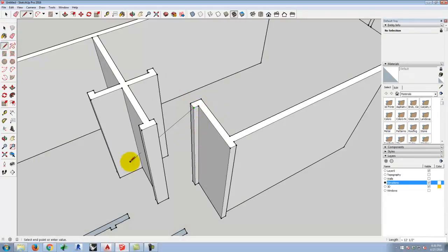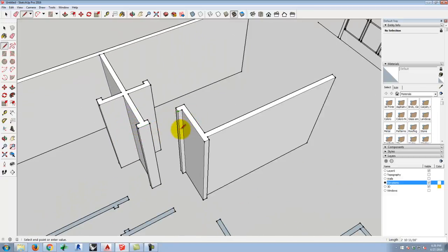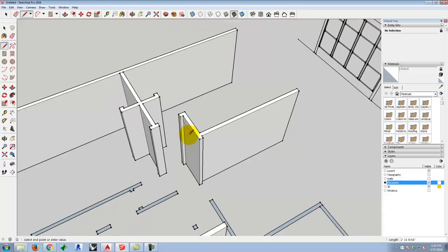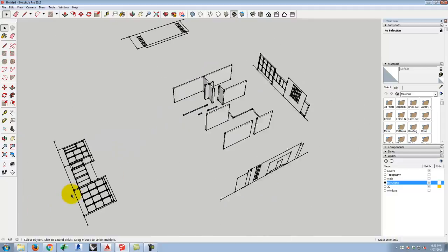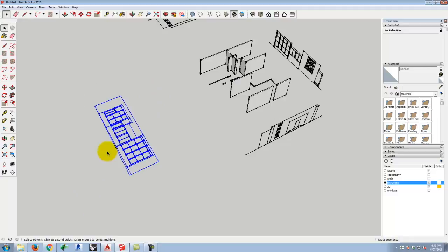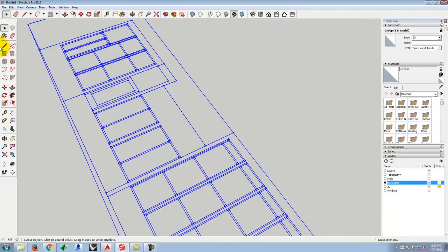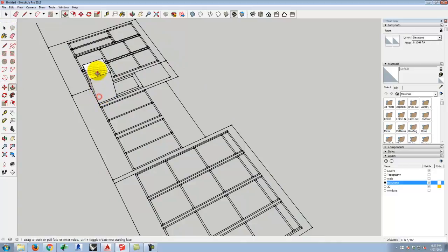So in this instance, my door is probably down at the 8-foot level. I forget what the distance was here. Bear with me for just a second. Actually, you know what? I have the door height right there. So let me rotate this into its view. So we'll go ahead and do a box, and we will push-pull that box up there.